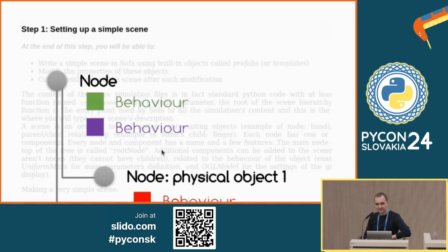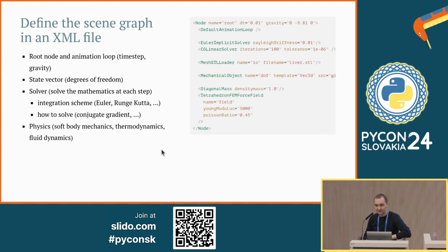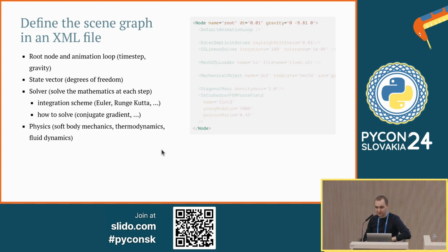So you need to define the scene in SOFA first. And how to do that in XML? Well, as I said, there's a root node which is responsible for defining the time step of the scene. Of course, it's not a continuous simulation, so this world is discretized. The world which we can simulate doesn't happen smoothly, but based on the phenomena, we know that, for example, some things are not going to be quicker than some time, maybe 1 microsecond.